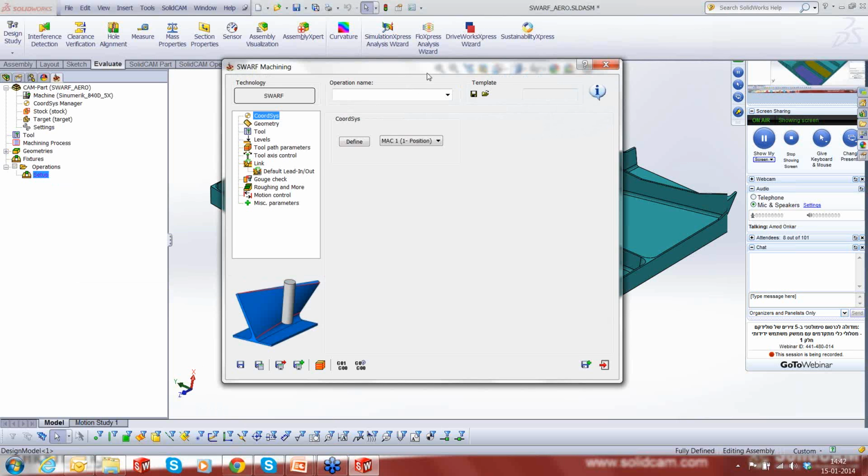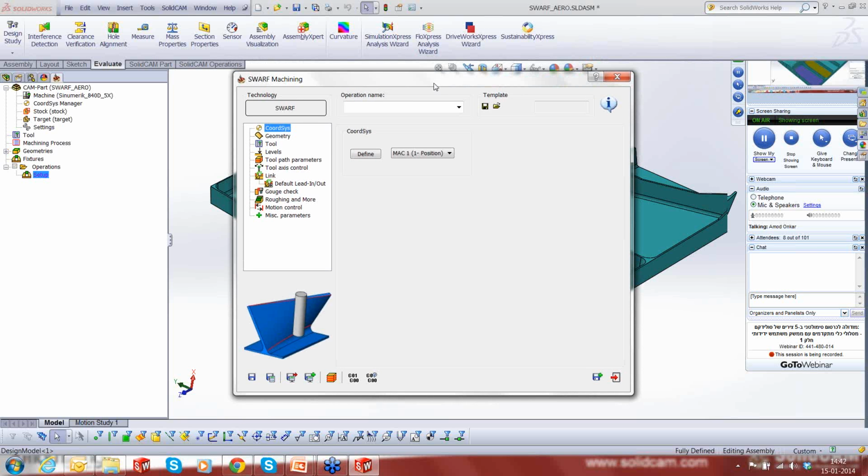The new functions that have been developed inside SolidCAM 2013 now take into account minimum input from the user. Because if you look at our regular 5-axis function, one needs to input a lot of things, including the geometries, the tilting geometries, check surfaces, angles, tilt angles, lead angle, the step order. A lot of things have to be input before you get to generate the program. But with the new engine of swarfing, you really don't have to worry about the inputs, because the inputs are bare minimum in the newer functions of SolidCAM.